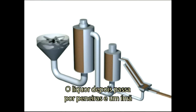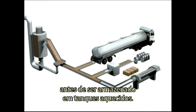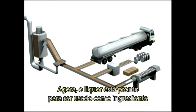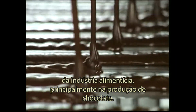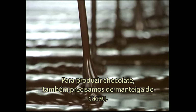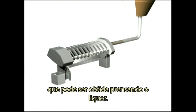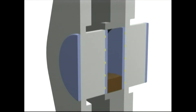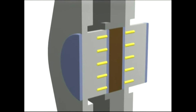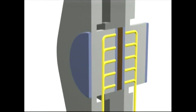The liquor then passes through sieves and a magnet before being stored in heated tanks. The liquor is now ready to be used as an ingredient in the food industry, mainly for chocolate production. In order to produce chocolate, we also need cocoa butter, which can be obtained by sending liquor to the presses. In this phase, hydraulic presses separate fat from the cocoa solids by forcing the liquor through a filter screen at a high pressure of up to 500 bar.